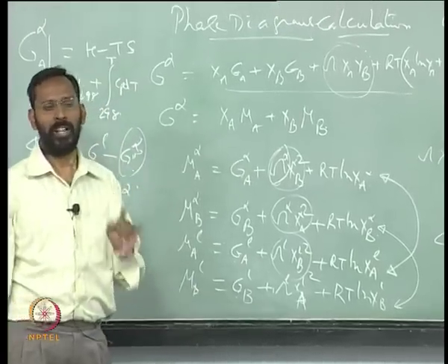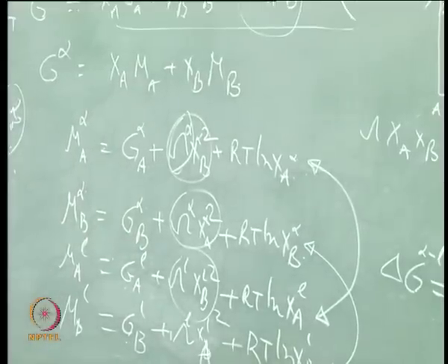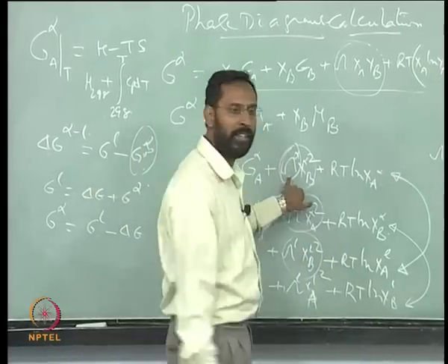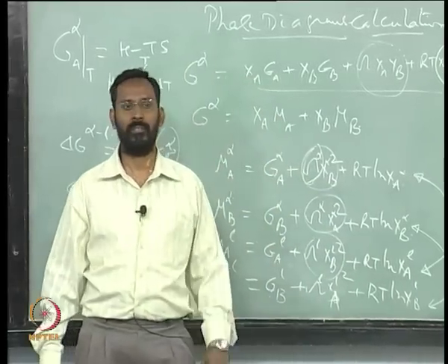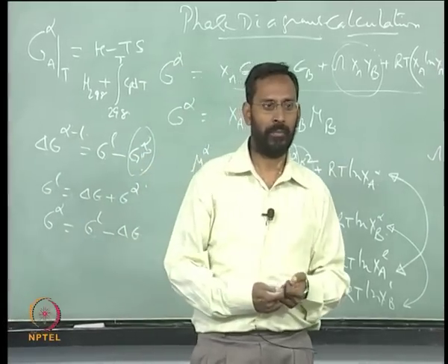But one thing that we always assume in all these calculations is that this is not changing. Again there is an assumption. In fact, if you go to basic CALPHAD calculations, people have actually done it. What I mean by a problem here is, what is omega? Omega is nothing but the interaction between A and B, let us say, am I right?